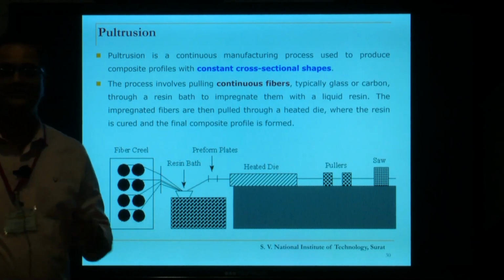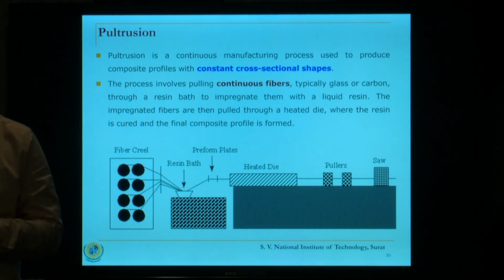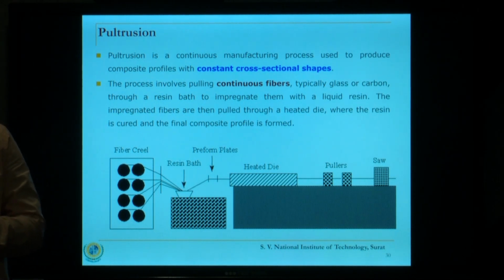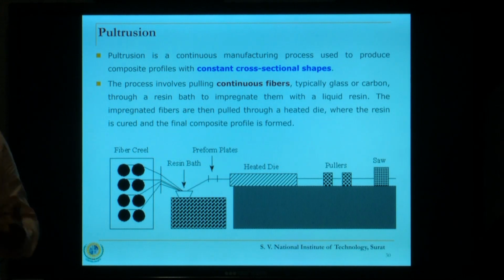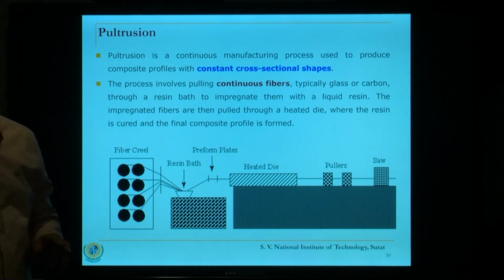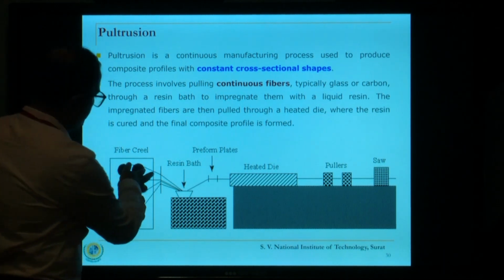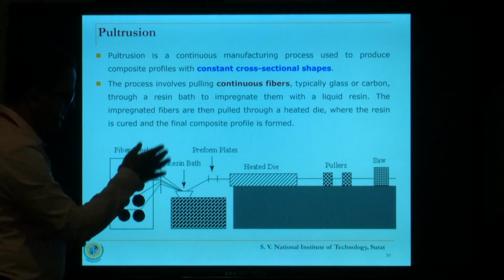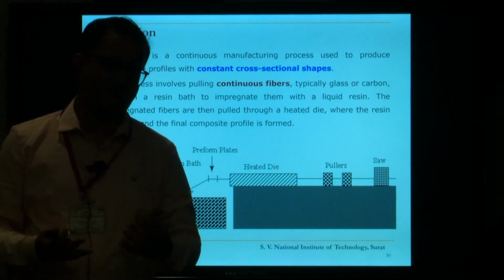The way these textile industries work, they have multiple threads and they combine together. So, you may always admire a shirt which has 6-7 colors into it, multiple designs into it, but all those things come through multiple yarns, multiple threads, and they are put up in a specific fashion. Similarly, here also we use continuous fibers, threads are used, and they are put up in a certain way, so that they are brought together as a yarn, they are passed through the bath of resin, and then they are allowed to pass through a die. Whatever die you have, it takes that shape.